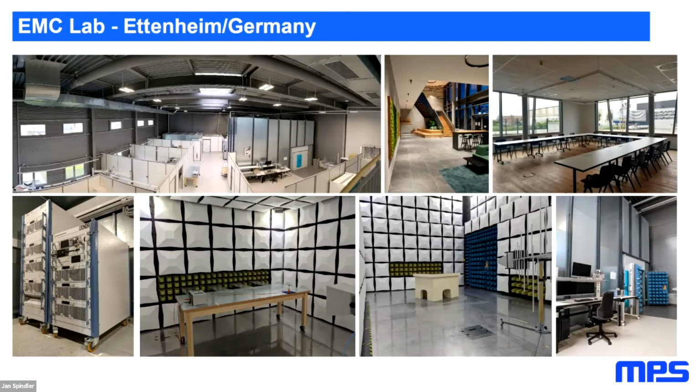A cylinder of 2 meters, so it means the product can be so big to be fully compliant on this. Yeah, and then you need to see the whole DUT. You need to get the antenna at a higher distance to see the whole product, and that's why you're talking here about the 3-meter topic.